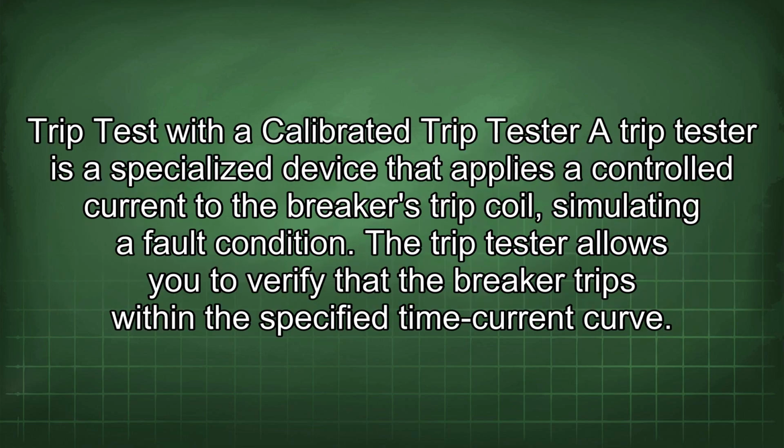Trip test with a calibrated trip tester. A trip tester is a specialized device that applies a controlled current to the breaker's trip coil, simulating a fault condition. The trip tester allows you to verify that the breaker trips within the specified time current curve.